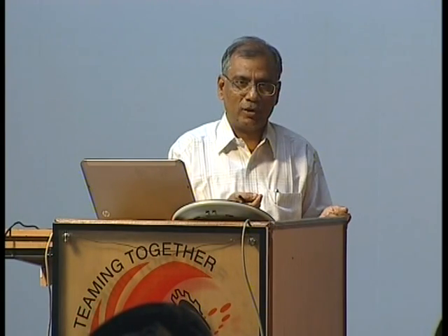People are saying that we are going to levels where it is difficult to measure. You are asking for a level of soot which is so small that I cannot measure and say that it is that much. We are going to the limits of instrumentation. And now people have started counting the number of particles. So the next level of norms is going to be with so many particles of soot coming out of the engine. It is not size, it is not quantity, it is number. So you need to have an instrument which will count. So it's coming.